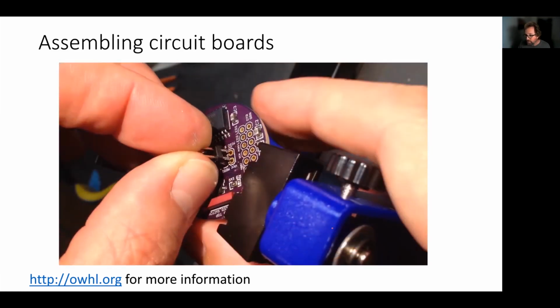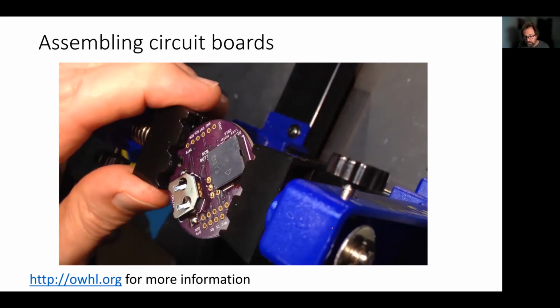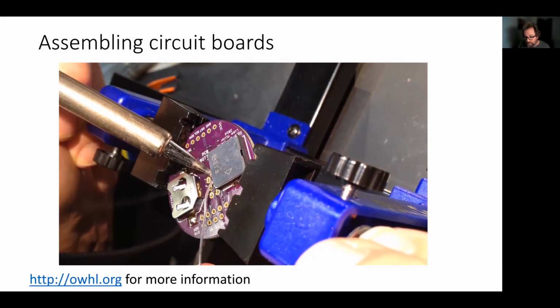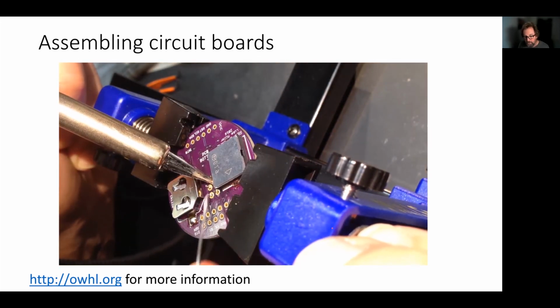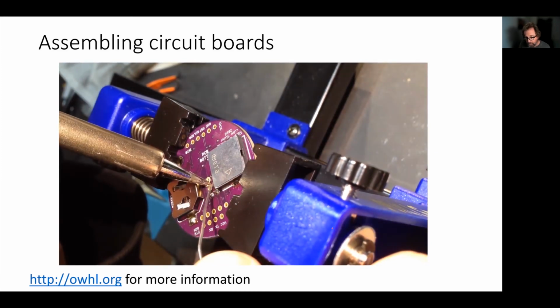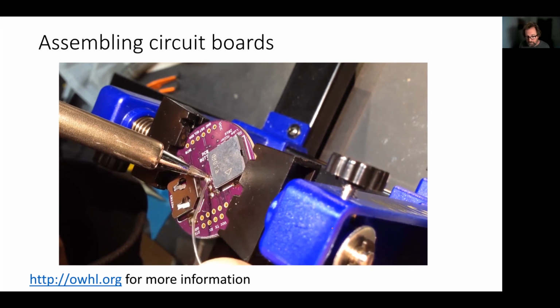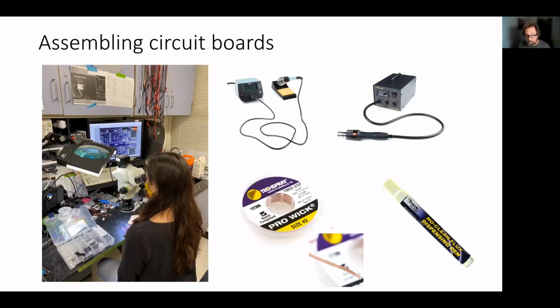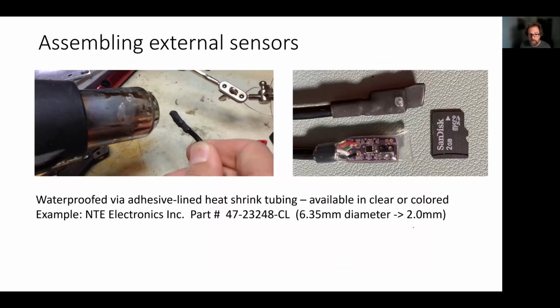In this case, there's often these other through hole parts that need to be soldered on by hand. Here I'm using that old-fashioned solder with a soldering iron to attach these extra parts. And that gets you the final completed device. You might have those extra steps where you again need that soldering iron, or a hot air rework station might be useful for cleaning up messes, too much solder in some cases. So solder wick and flux are also useful tools at this stage.